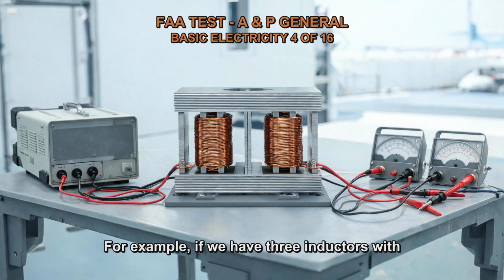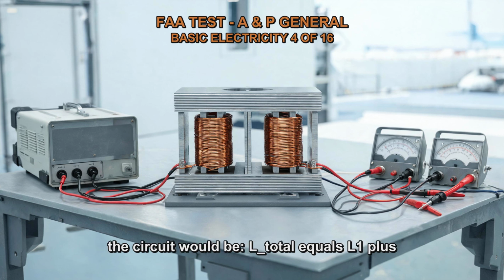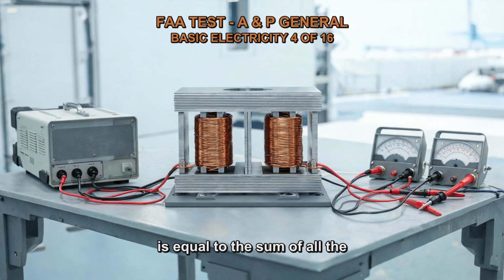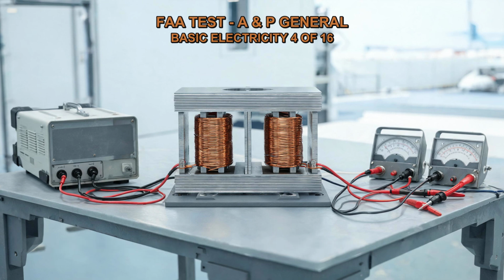For example, if we have three inductors with inductances of 1 Henry, 2 Henrys, and 3 Henrys connected in series, the total inductance of the circuit would be L_total equals L1 plus L2 plus L3. L_total equals 1 Henry plus 2 Henrys plus 3 Henrys. L_total equals 6 Henrys. So the total inductance of the circuit is equal to the sum of all the individual inductances, regardless of their individual ratings.